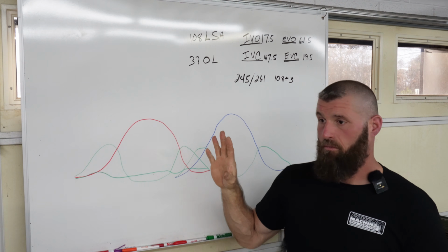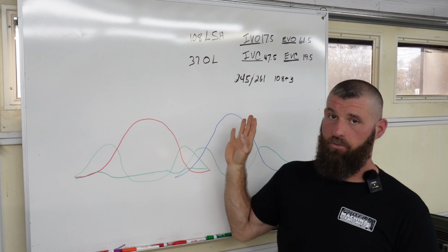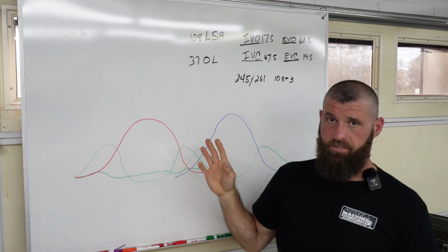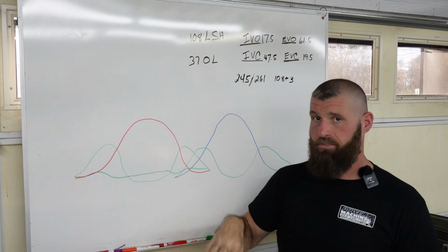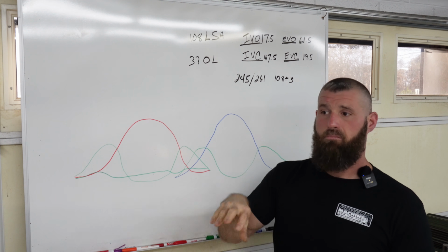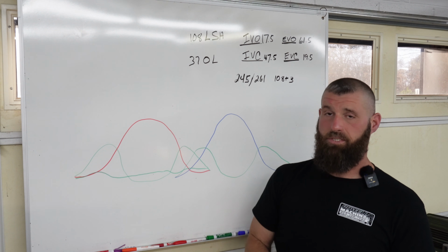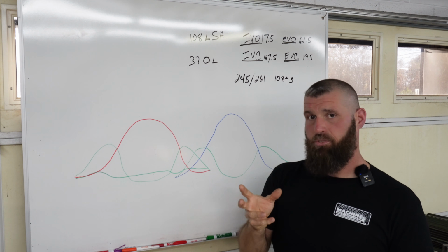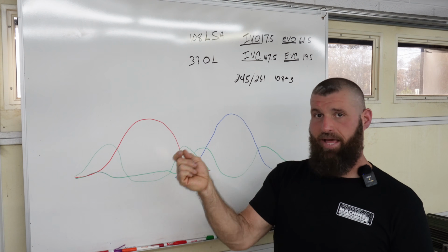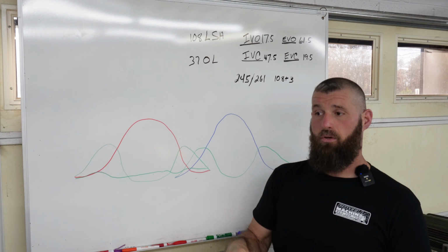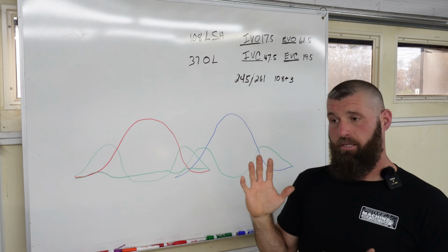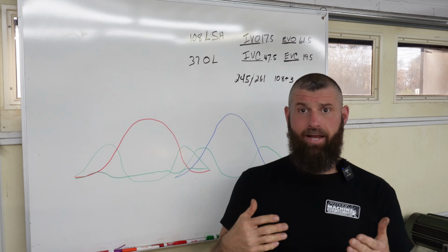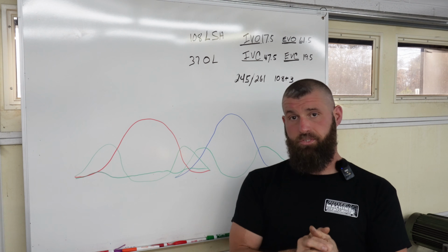So I redesigned these lobes. The 50s are the same, lift's the same, lobe separation, intake center line, all of that stuff's the same. But we was able to get a little more positive acceleration, and I'm interested to see just how much power, if any, that is going to give us. And so I asked Bob, I said, hey, if I do another cam, can we back-to-back test the old cam versus the new cam same day?